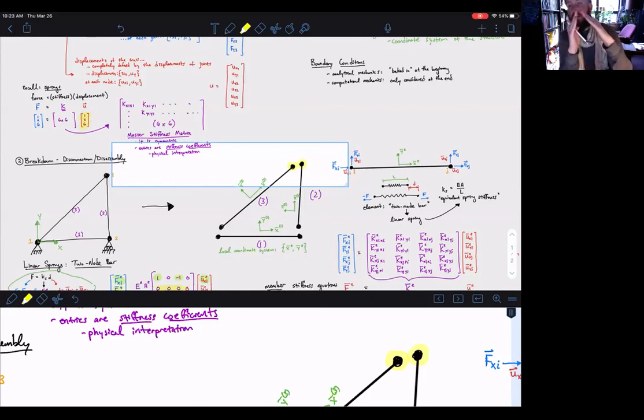Let's try it again. So your diagonal truss, in response to a force this way, will have some X displacement, which means this node in response to a force this way will have some X displacement because of this connection here. So it's not that this node has 0 displacement in the X direction. It's that as it's loaded, there's no translation of this force that can cause any X displacement of this node. But because it's connected, it's not actually 0. I got it. Thank you.